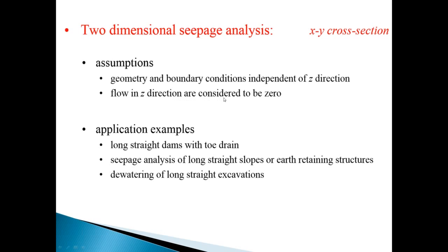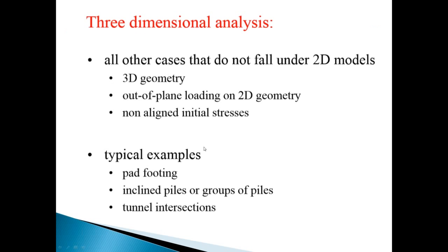So all flow has to be either in the x and y direction. Otherwise, you need to do a 3D analysis. And then application examples: long straight dams with toe drains, slopes and retaining structures, dewatering of long excavations, and then also embankments and earth dams as well.